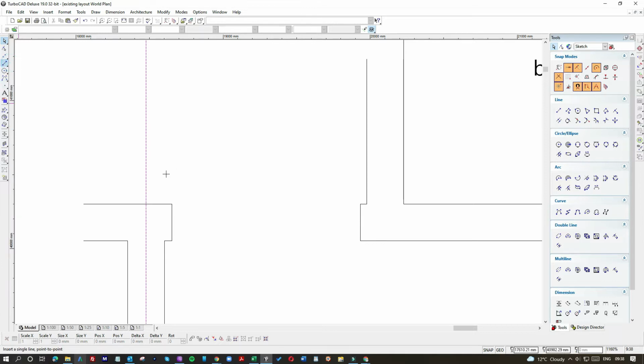Now, if this would be the external part of the wall, the new wall would be a blockwork wall, which is 100mm blockwork and then a 100mm cavity filled with insulation, and then an inner layer of blocks, another 100. So effectively 300, but we also have to allow for rendering and plastering.